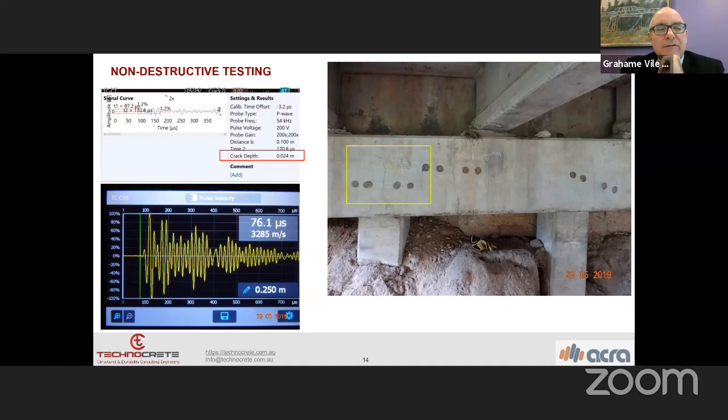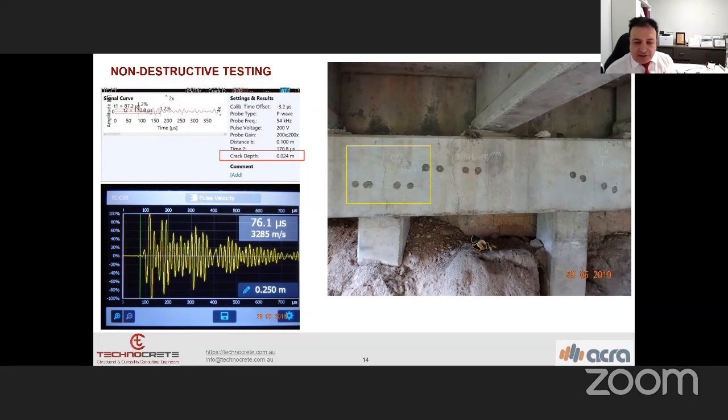No worries. And if you don't have the initial design or as-built documentation, how do you accommodate that lack of knowledge? Yeah, it's a common problem. Most of the structures, with 40, 50, 60, 70 years of age, don't even have drawings. Then we have to obtain all of that information with non-destructive testing, for example the size of the rebar and the arrangement of the rebars, and we have to do specific site measurement in order to be able to model the structure. Yeah, so it increases the investigation.